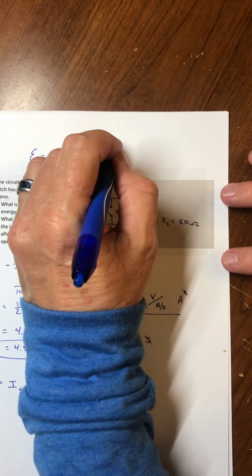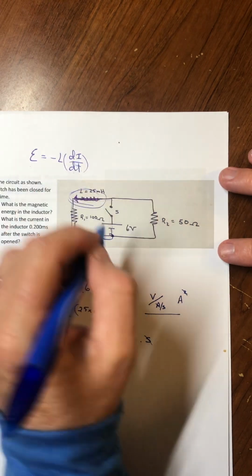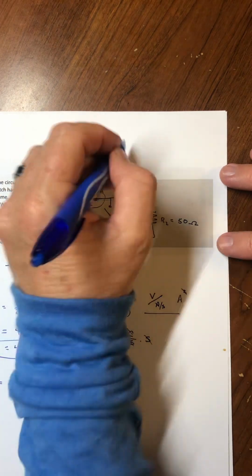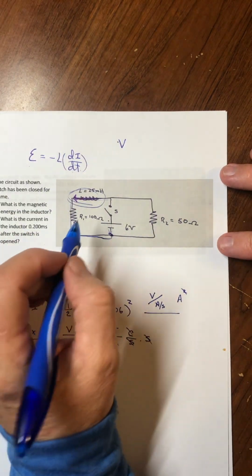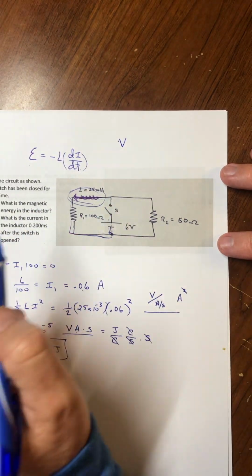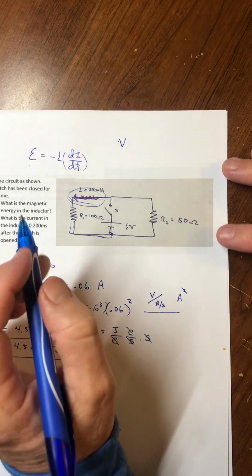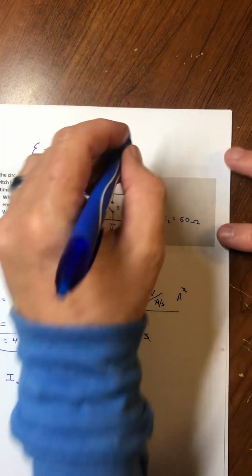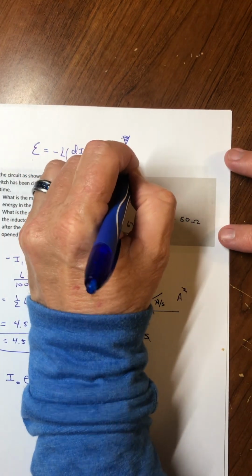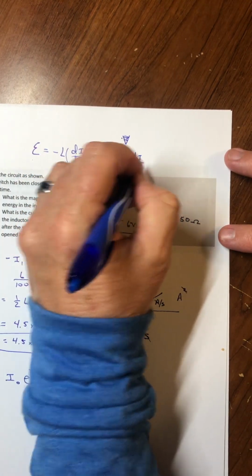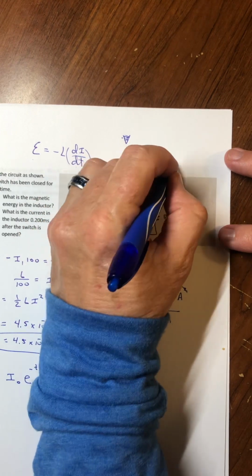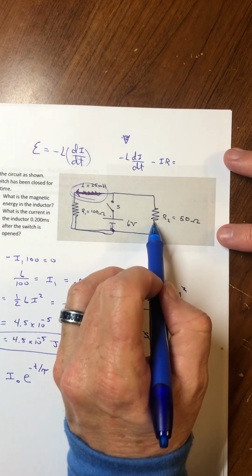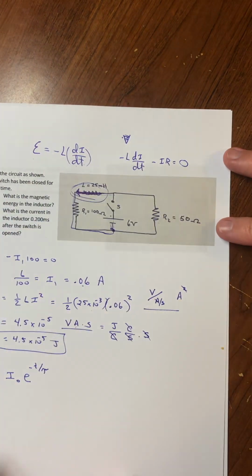You would have the voltage here. Well, that's with the switch opening. When it's closing, I guess you wouldn't have a voltage. You would just have the voltage from the inductor and the voltage from the resistor, or in this case, and this is what I want to emphasize, it's going to go around through this second resistor, equals 0.